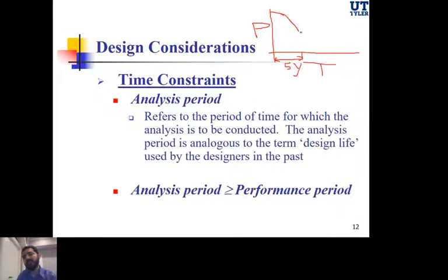And then at the end of the 5 years, we said, well, you know what, we need to do some maintenance. I'm going to apply maintenance. Let's say a 2-inch overlay is going to pump up the performance of the pavement. Not again, not to the original condition, but at least a considerable improvement. And then this 2-inch layer is going to last maybe for 7 years before it reach another failure. And let's say at this point we didn't have enough money to do another 2-inch layer. We did a very minimal surface improvement that's going to pump up the surface this much, and then in 2